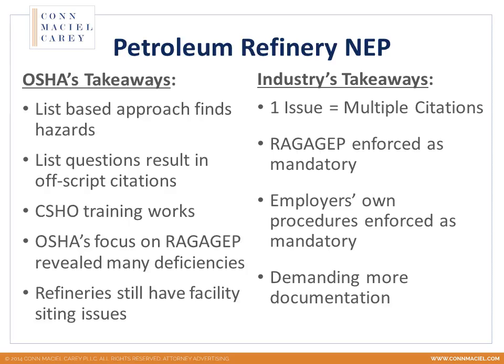And what we would see is someone would make a valve replacement, and that might trigger a violation for management of change, not doing an adequate management of change for it, not updating your process safety information based on a new valve or new materials of construction. If the valve requires a change in your standard operating procedure, not seeing an update in the procedure, and then likewise, therefore, not providing required training to your employees. So one activity, one event leading to multiple violations, all of the same activity. That was one of the big takeaways of the NEP.